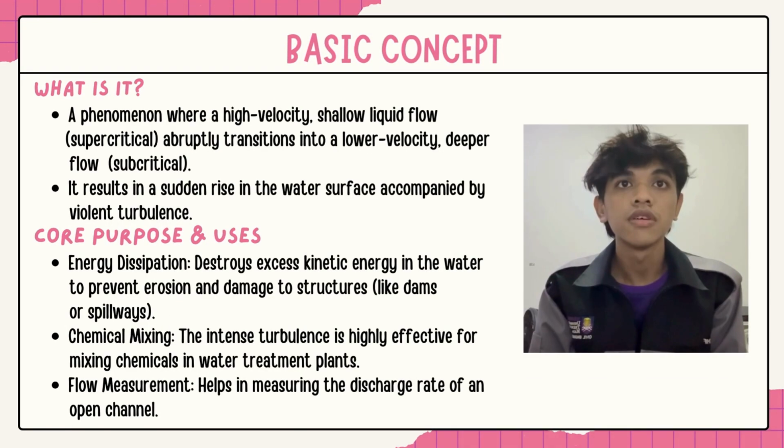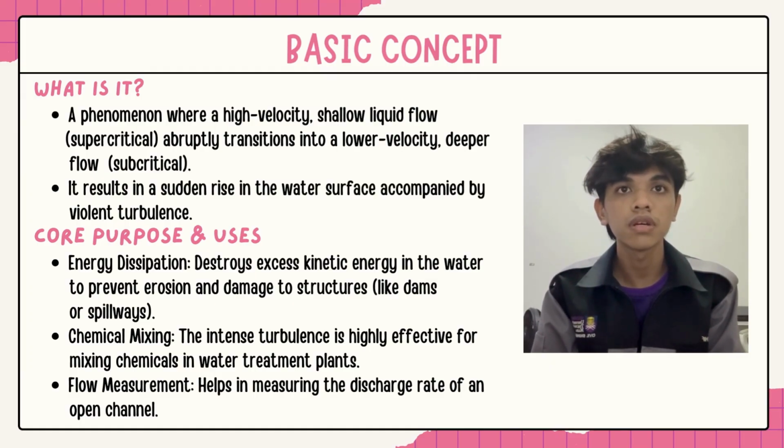What is a hydraulic jump? A phenomenon where a high velocity, shallow liquid flow, supercritical, abruptly transitions into a lower velocity, deeper flow, subcritical. It results in a sudden rise in the water surface accompanied by violent turbulence.